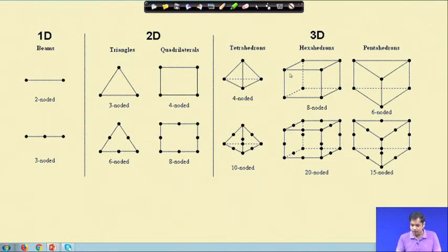But there are some efficient ways also to construct these F functions. Now, the common thing in all these F functions, whether it is for 1D, 2D or 3D, is that when we construct the F function, we assume that the displacement, the degrees of freedom, the field variable, is approximated through a polynomial.